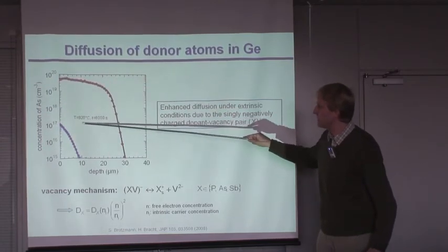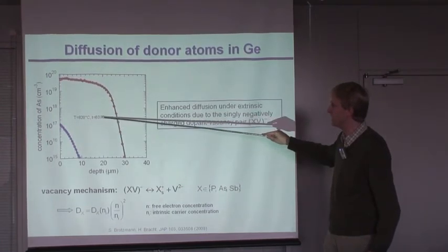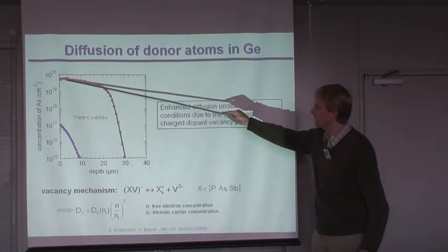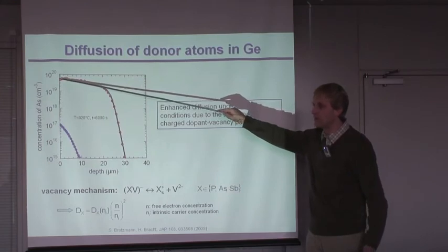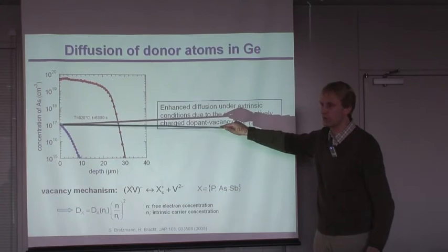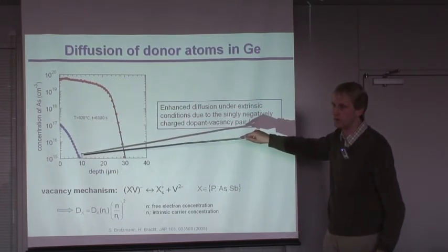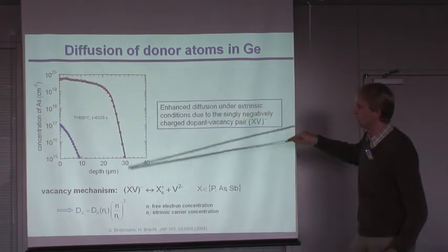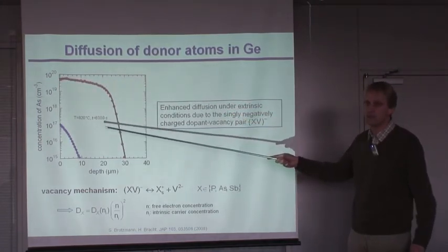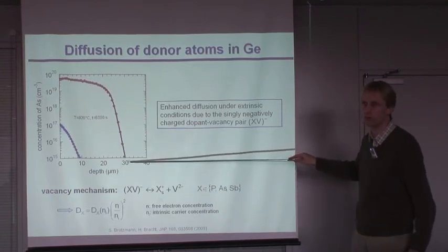But here you see it's the same temperature of annealing. So you take this temperature and this time, and if you establish a very high surface concentration, you get this profile. If you establish a very low concentration, you get this profile. This profile is a complementary error function, and this is a so-called box-shaped profile. But you see immediately it's totally different, the profile shape, and also the penetration depth is totally different.